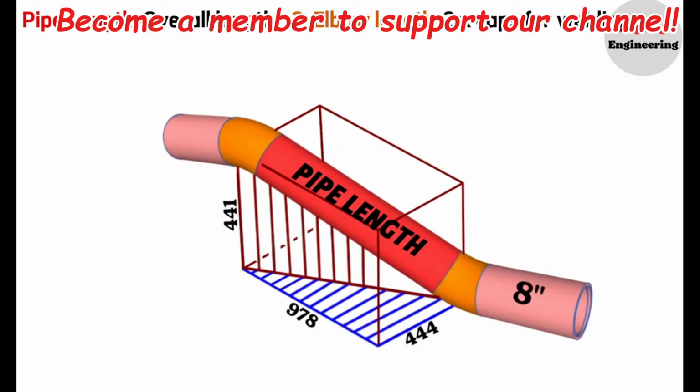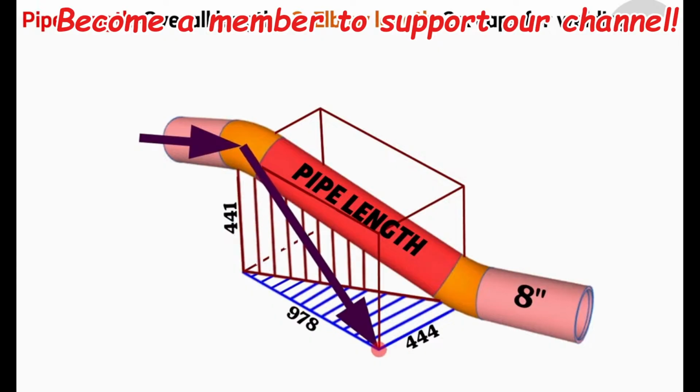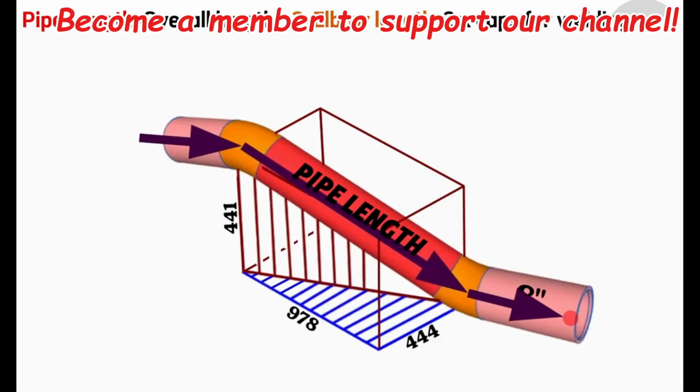In our previous videos, we explained that the double rolling part of the pipeline is easier to understand when visualized within a right-angled parallelogram. As you can see, the 8-inch pipeline extends southwards. At the top right corner of the parallelogram, the pipeline first descends by 441 mm, then continues southwards for 978 mm before turning eastwards for 444 mm. Finally, at the bottom left corner of the parallelogram, the pipeline again continues southwards.